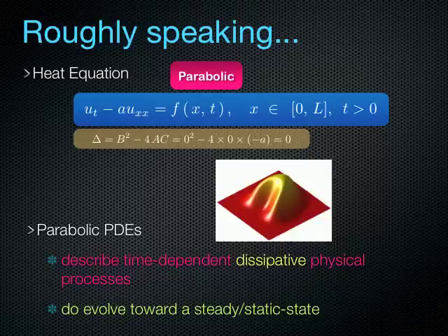And this equation in the blue box describes that solution at the steady state. So this is, if you will, the pressure distribution inside a porous medium. And then let's say that this is some well or a pipe that is generating some water pressure into that porous medium. And then a certain time has already passed, and this solution has reached that steady state, and this pressure distribution has stabilized. And this equation inside the blue box is precisely describing that final solution.